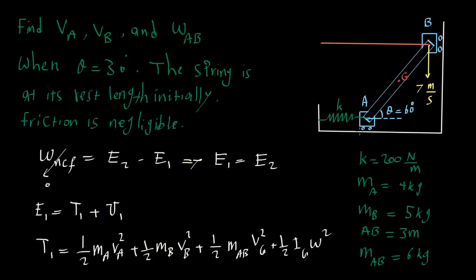And the velocity of A is in the horizontal direction, and perpendicular to it would be the vertical direction. So basically this is the instantaneous center of rotation here. Let's show it with IC.